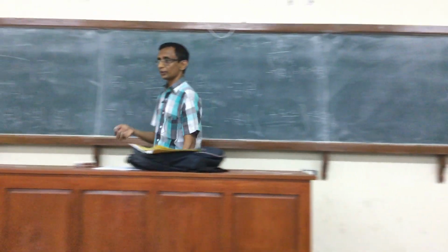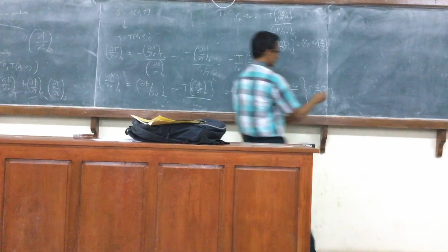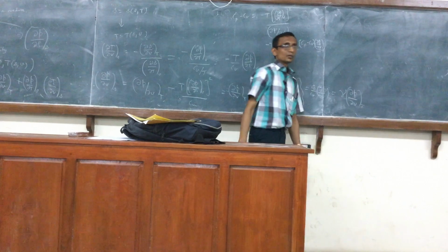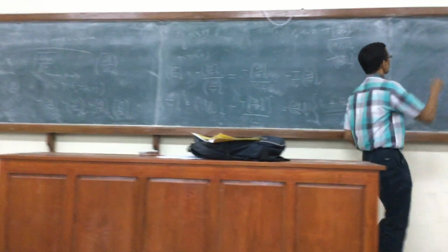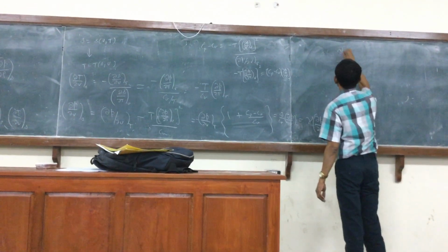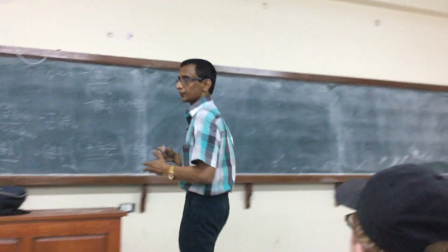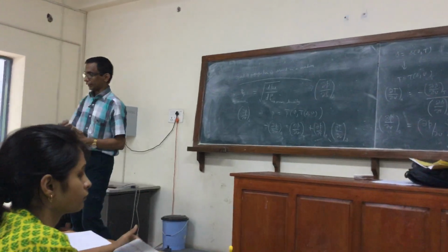The Cp by Cv is a new factor, the gamma, the ratio of specific heats, right? So what we now get is dP by dV at S is gamma times dP by dV at T. This is an important formula. What we have done, because what we want is any coefficient, wherever possible, we want to express in terms of Cp or Cv or both, and equation of state derivatives, quantities. And so that's what we have done here.